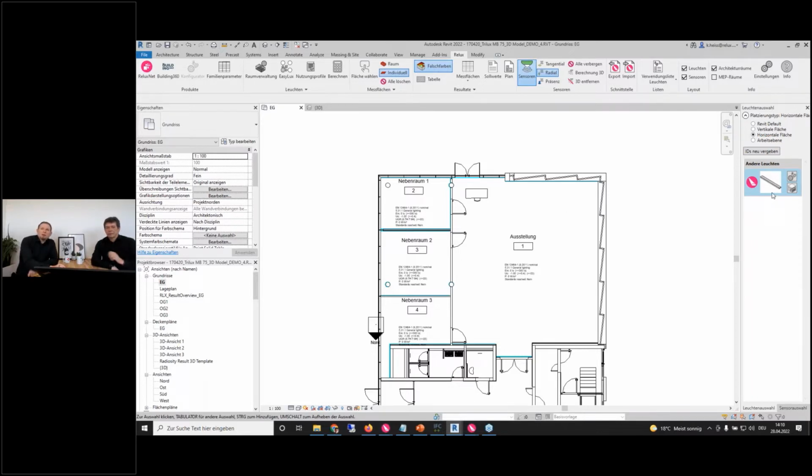So, and now I want to have a calculation. I can also drag and drop this luminaire now into this room and have a photometric calculation. But I did not want to place it by hand. This is a bit more painful in Revit than in Relux Desktop. So there are no big helping tools like in field arrangement or something. There is a field arrangement in Revit, but to find the right level to input these luminaires and so on, this is a bit more tricky. It's possible, but it's a bit different than in Relux. And so, yeah, I try to avoid this.